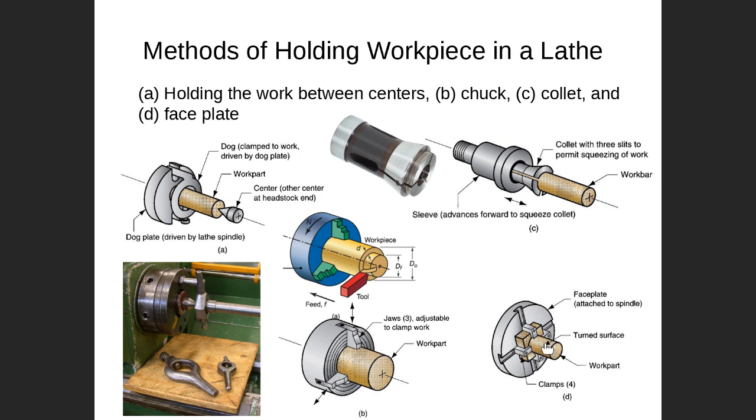Then why do we do that? Because of irregular shape. This one has an irregular shape. You will ask me how to locate the center in the middle by using the tailstock. They usually use the tailstock to hold the center in a position and then clamp by using these 4 jaws. In this way, you can ensure that the center will be exactly in the middle.